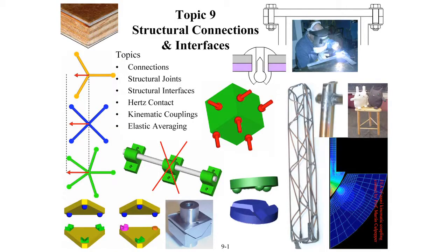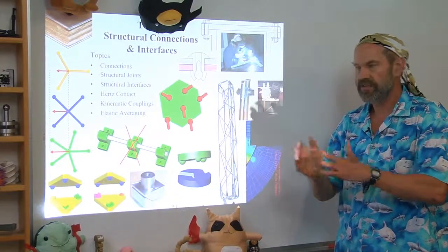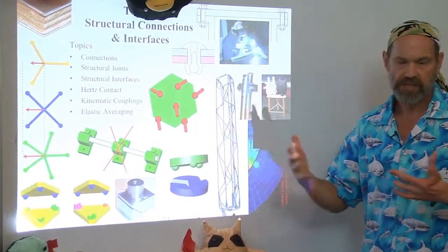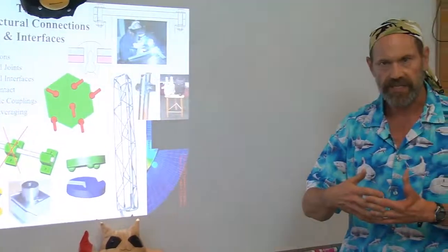You have to meet a structural or physical strength or stiffness requirement, and when you put it together, it's either going to be aligned afterwards and then tightened, or it's already aligned and then you attach it. There are various types of these joints, from the structural, bolted, welded, pinned, to couplings, toothed couplings, magnetic couplings, contact to non-contact. We're going to be focusing on mechanical contact joints in this particular topic.